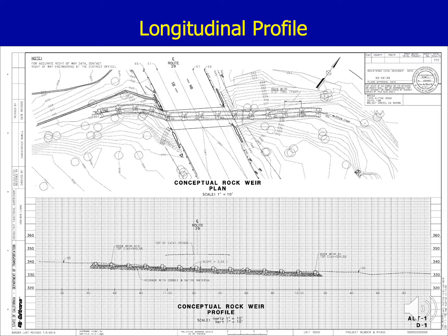If there are another couple more of them, as soon as this crossing comes out, they're likely to be moving upstream, and you can see already we're going to compromise the depth of the boulder weirs. When you start bringing up scour through the boulder weirs, it's pretty common to lose the downstream one. This is the downstream one that goes off in the whole project on zips.